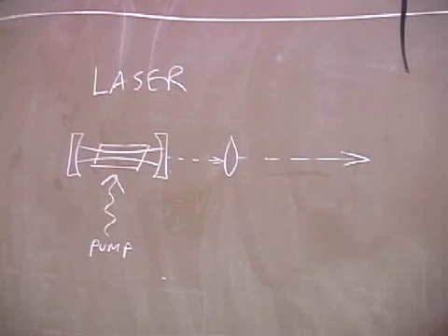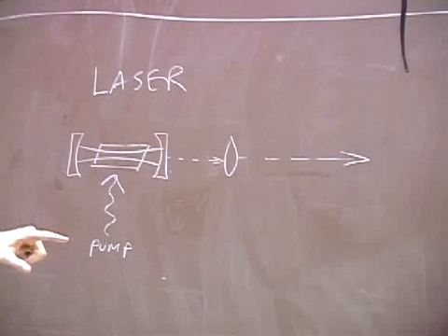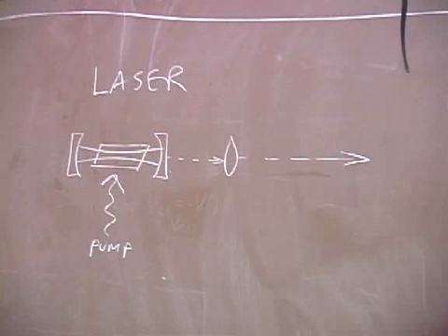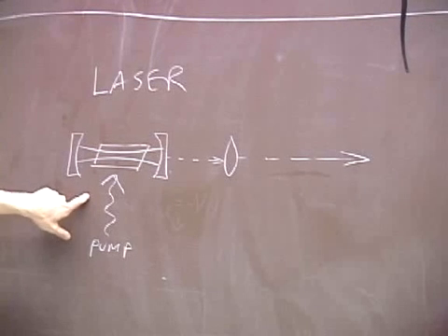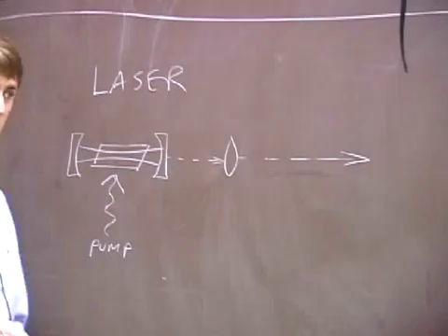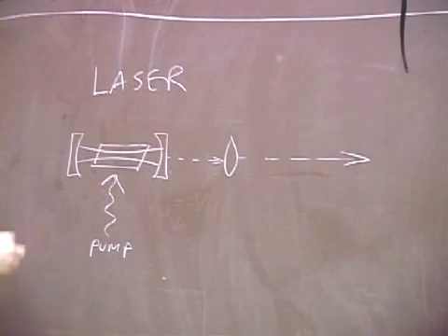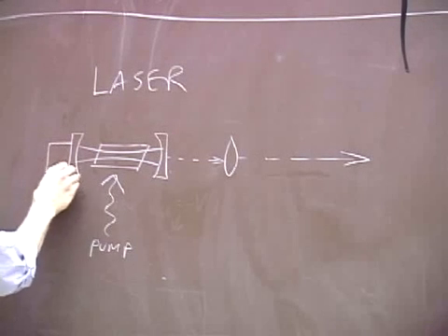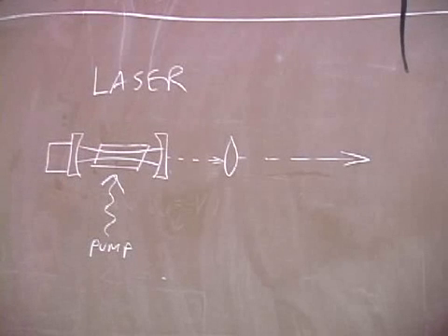But just like the thermostat, we don't really want to calculate heat transfer in your apartment. We want a control system which you can just set. Say, I want the temperature to be 78 degrees here. Well, we can do the same thing with a laser. We say, I want the frequency to be, bang, exactly 1,064 nanometers to a part in 10 to the 6 or whatever. And for that, we need two things. We need a way to act on the laser, change its frequency, and a way to measure its frequency. And then we need a way to couple the two.